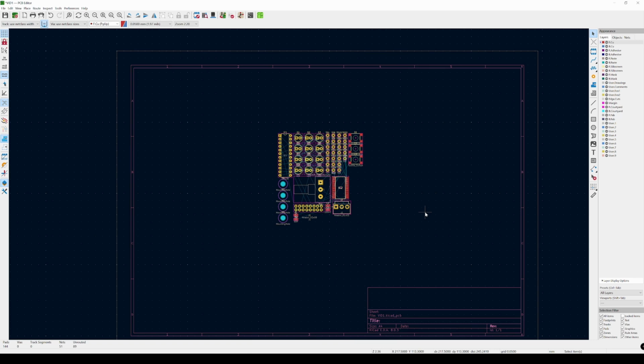So first things first, after the components are exported, you want to define the confines of the area that you are going to be working with. In my case, we have a very specific size limit for the PCB, since there is not a lot of space and the components need to be in specific spots. And generally speaking, smaller is better, since smaller is cheaper.